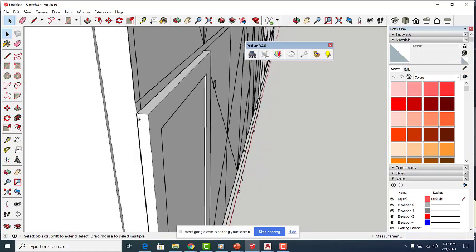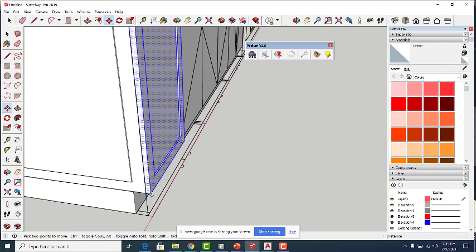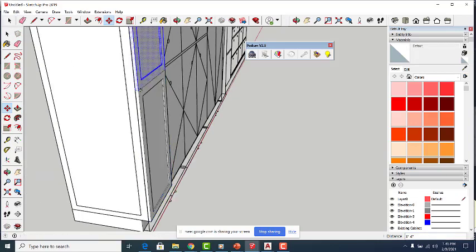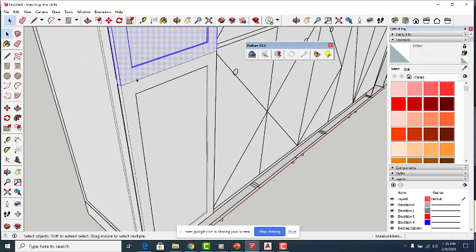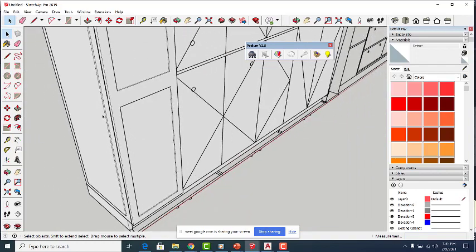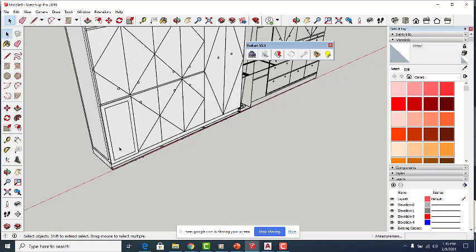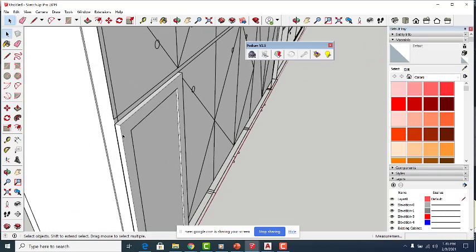Again, if I have the same door here, you see the line when you render it, this would be one piece. When you render this, that's what you see, just one big door. So please guys, if you haven't done it yet, from now on, every time that you have a door, add a little bit of beveled edge on it, and it's really simple.